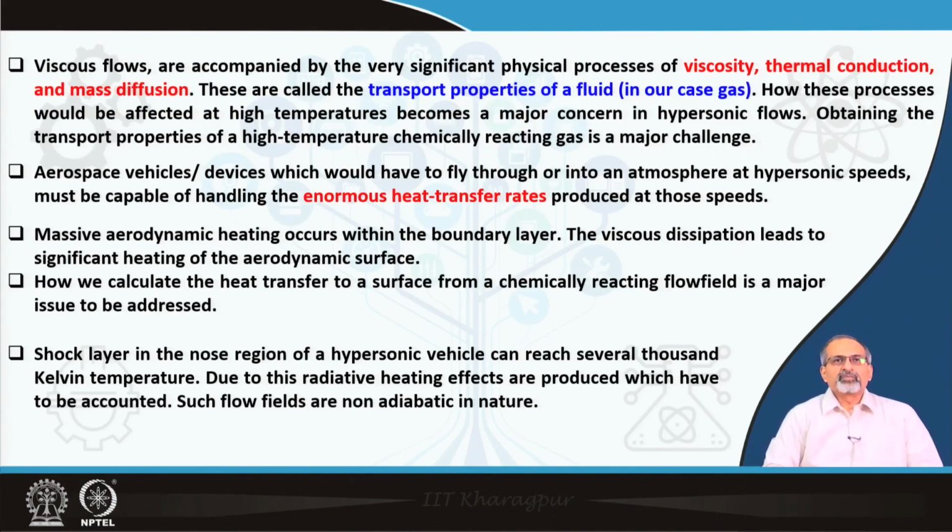Starting with an overview, viscous flows are accompanied by very significant physical processes like viscosity, thermal conduction, and mass diffusion, and these are called the transport properties of a fluid. In our case here in this course, we are primarily interested in gases, and how these processes would be affected at high temperatures becomes a major concern in hypersonic flows. And obtaining these transport properties for high temperature chemically reacting gas, of course, is a major challenge. We have to live with these challenges when we are dealing with hypersonic flow past different kinds of vehicles.